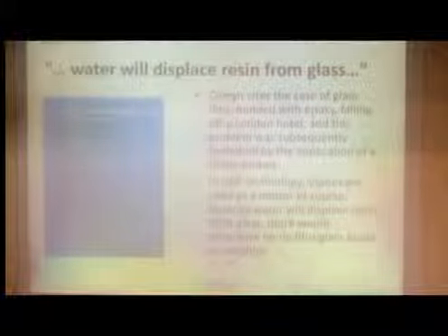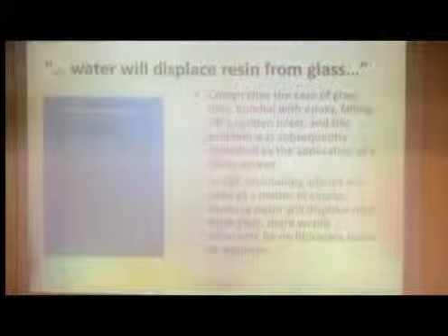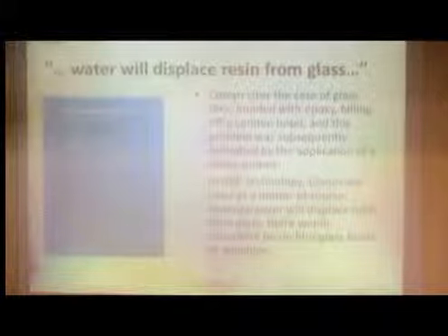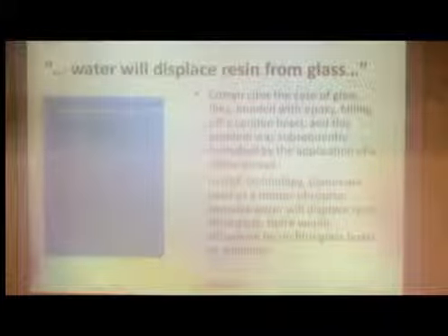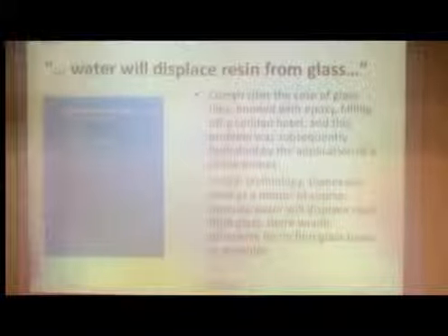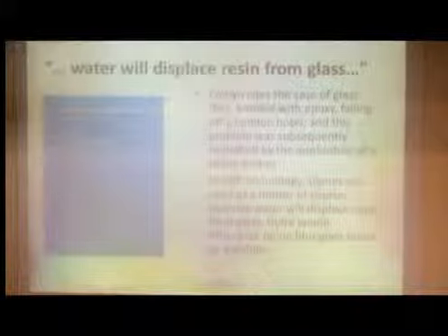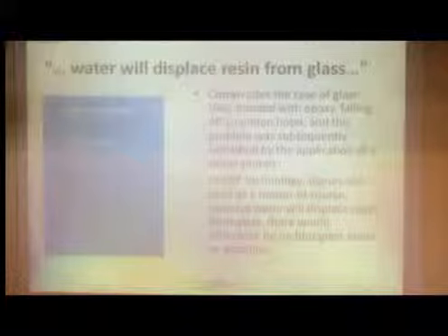And indeed, if we make boats out of fiberglass, which we do, then we know they don't sink, and the reason for that is that the glass has to have some sort of treatment. It might be a silane treatment, which means that the epoxy prefers to stick to the silane treated glass than it does to the water.